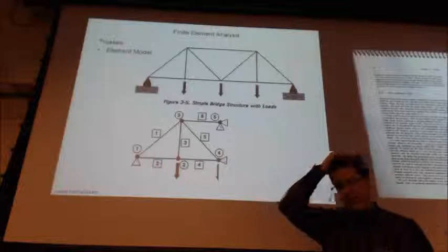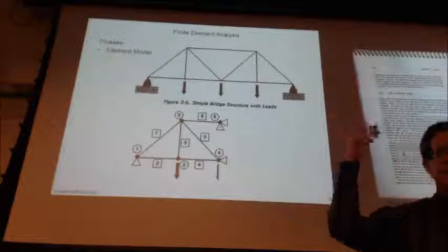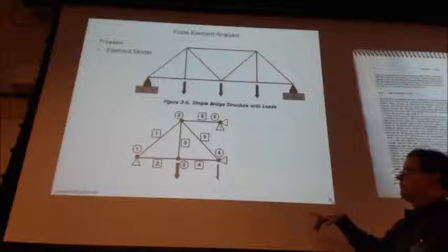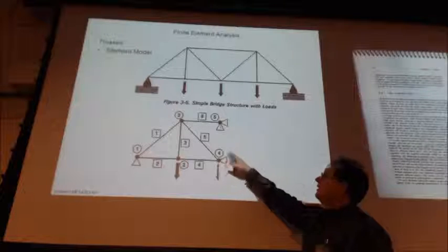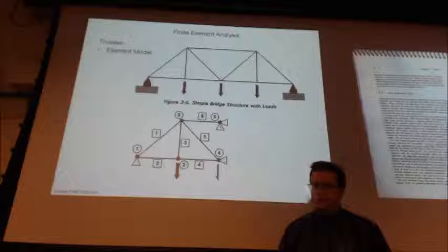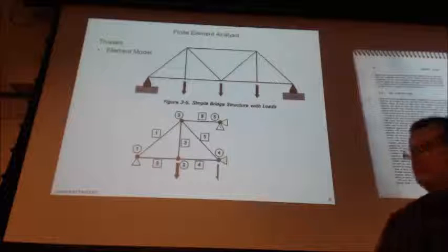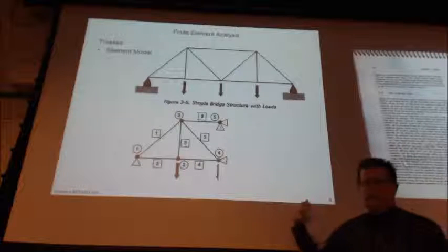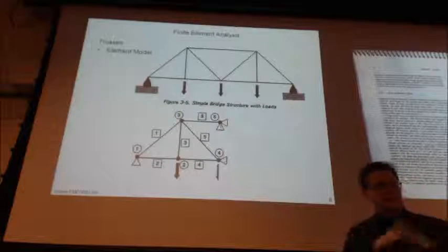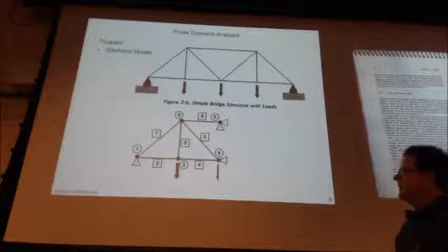And whenever you have objects that are symmetrical, especially if they're large and complicated, you can take advantage of symmetry to minimize the number of calculations and simplify your model. But you do need to constrain the line of symmetry appropriately so that it matches what would actually be happening if you had the whole device there, right?